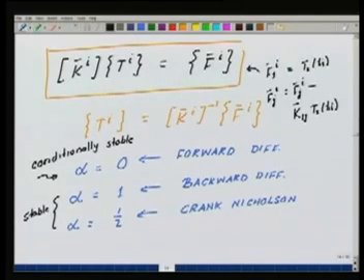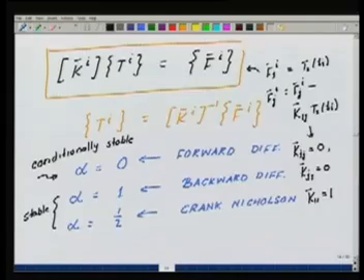This I will do, and after this I will set K1j bar equal to 0, Kj1 bar equal to 0, and K11 bar equal to 1. So I will do the same things that we have been doing till now for the static problem in order to enforce the boundary condition that the temperature at time t equal to 0 is given.